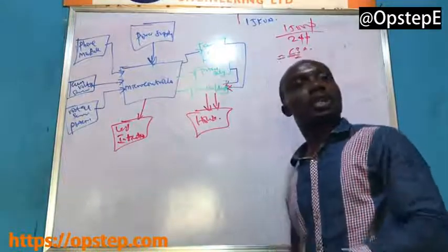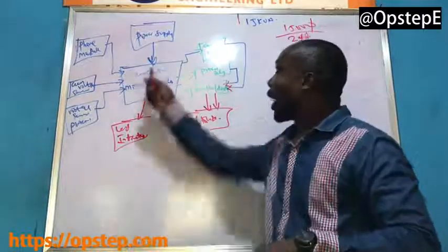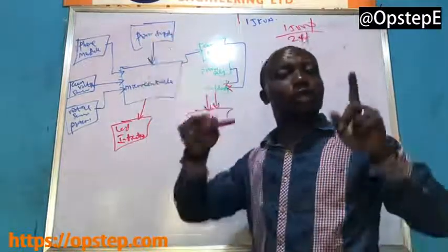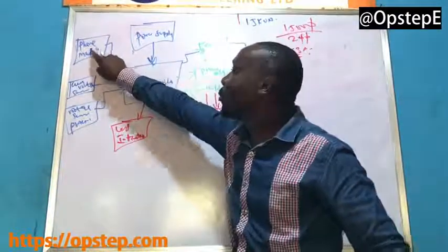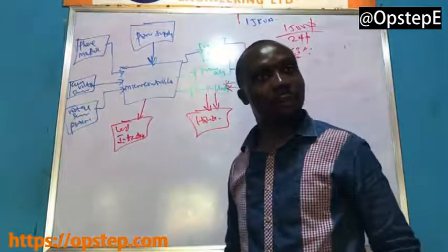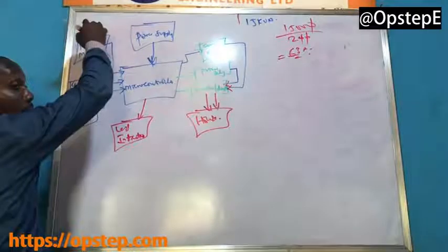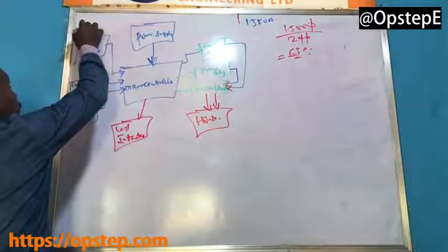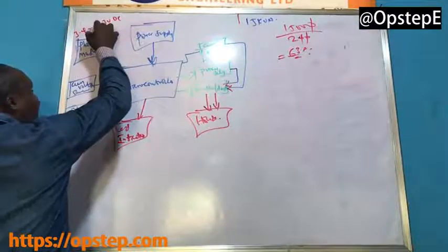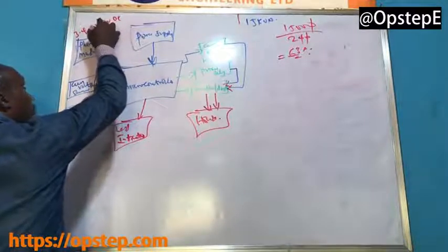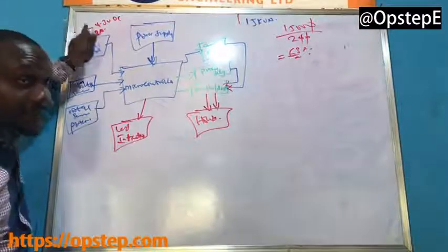Because in electronics, you go from the answer to the question, or from the question to the answer. I need a power supply. Before you draw your power supply, you need to know at what voltage the phone module requires supply. Are you with me? The phone module requires between 3.4 to 4.3 volts DC at 2 amps.